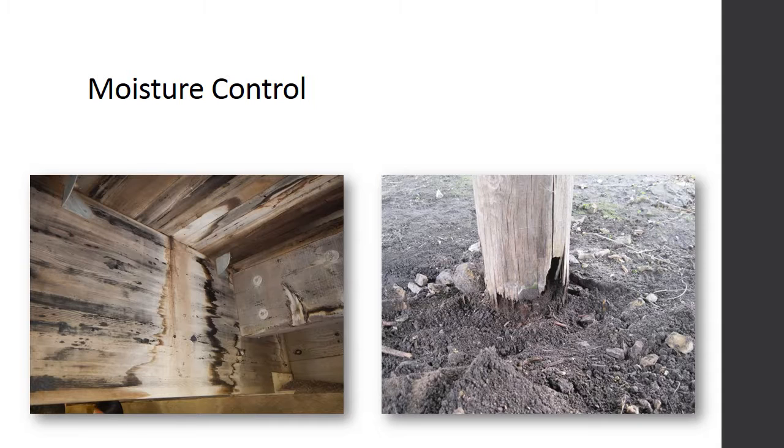When exposure to moisture is reduced, timber will dry to moisture contents below that required for fungus growth and that which is more susceptible to insect inhabitation. For example, generally speaking, timber abutments placed up and away from stream banks have an extended service life compared to elements near the stream that are repeatedly subjected to wet and dry cycles.